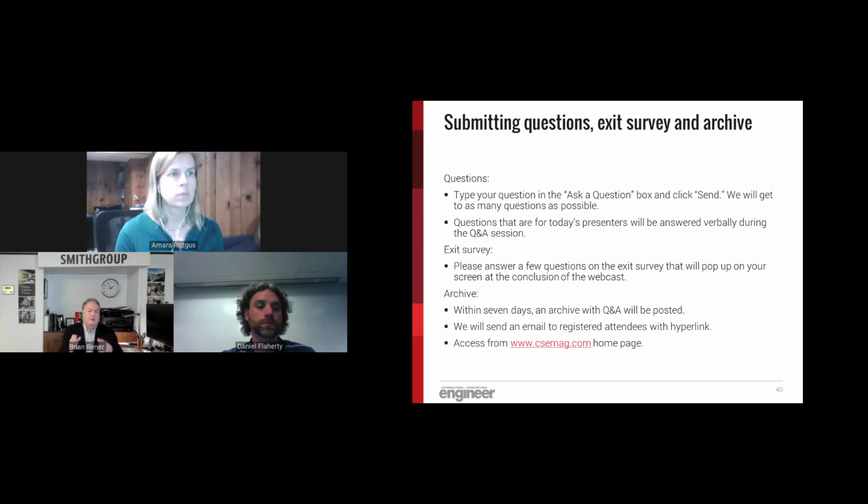You can put this hookup box, and you can hire an agency to come in every so often and actually place a resistive or reactive load. And I saw that as a question. It can be either. The code doesn't specify, although I do like having some reactive load. Or you can install the load bank permanently, so you never have to go to an agency. You never have to have a contract with someone. You've always got the load bank outside where you can test the generator on the load. And you have to keep all those records and keep them available only for emergency or legally required standby, not for optional generators.